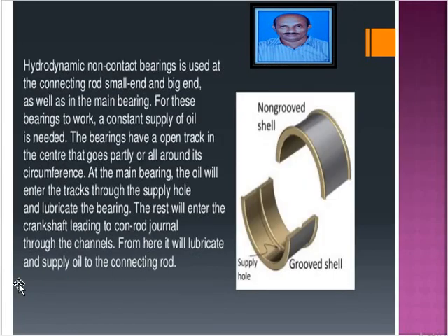You see how we use hydrodynamic non-contact bearings, with grooved and non-grooved shells supplying the hole. Please observe that. The oil will enter the main bearing, for lubricating the bearing. The rest of the oil enters the crankshaft. So the oil will be circulated whenever the engine is running.